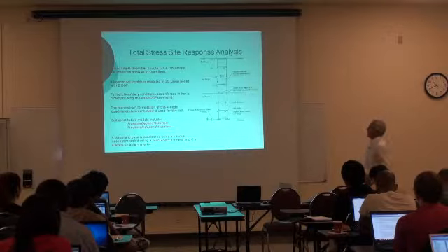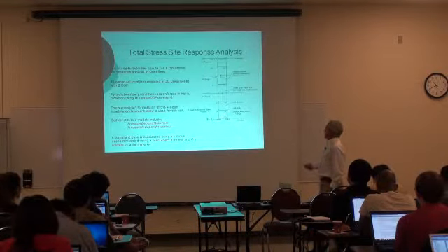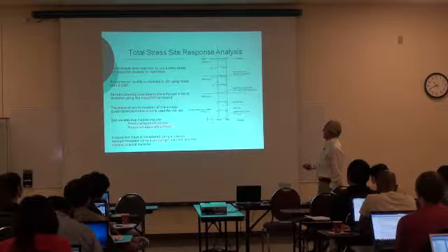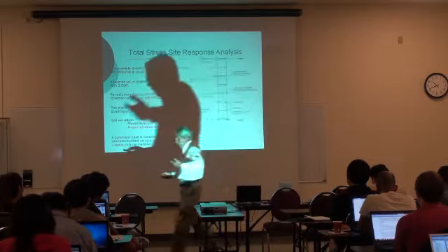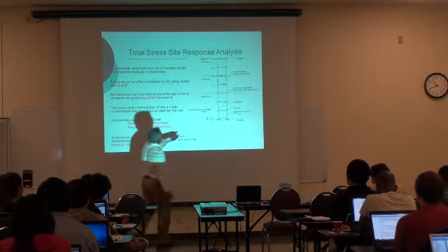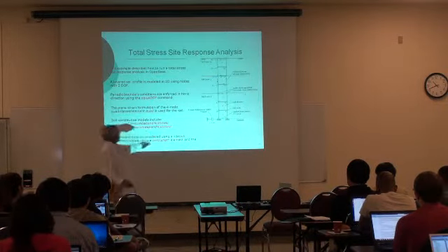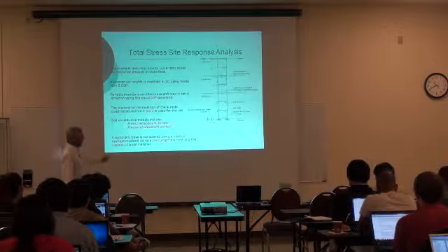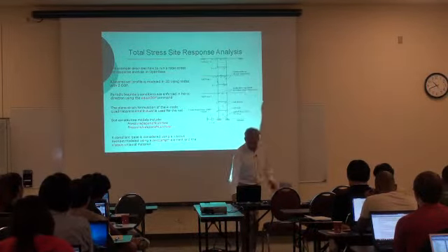In order to do that, what you have to do is to include a compliance-based situation. For doing that, instead of an acceleration here, what you impose is a force, and the force is defined in terms of a velocity. All that is described in Lysmer and Kuhlemeyer, 1969. Very old stuff, very useful stuff, by the way. And it's described also in the wiki how to do that.